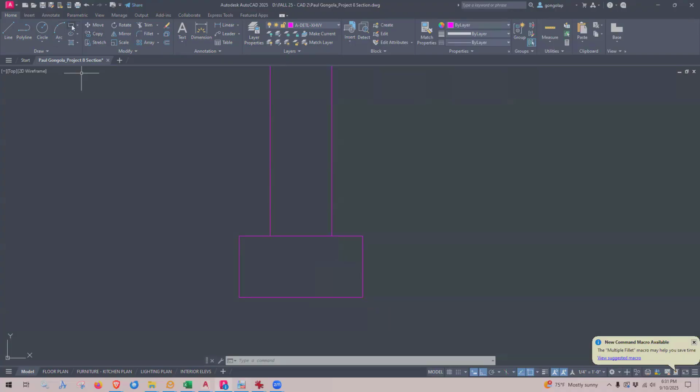I'm going to draw a little rectangle over here, and I'm going to make it 4.5 inches wide. I'm using the rectangle tool, and to get the horizontal 4.5, I'll hit my tab key, and that locks in the 4.5 inch width. And then I will do the height, which will be 1.5 inches. Oh, I'm sorry. It should be 2.5 inches. Let me redo that again.